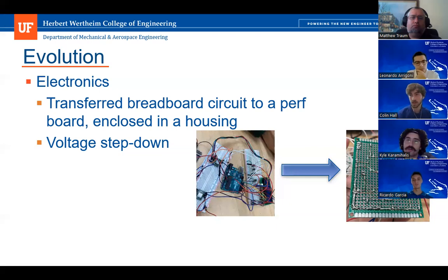While that is advantageous for most components and wires, we made sure to use inserts for the motor drivers because in the case one gets fried, or if we just have to replace one for some reason, you can easily take them out of the inserts rather than unsoldering every pin, which I think they have like 16 pins. Additionally, the perf board is a much more clean and condensed version of the breadboard.